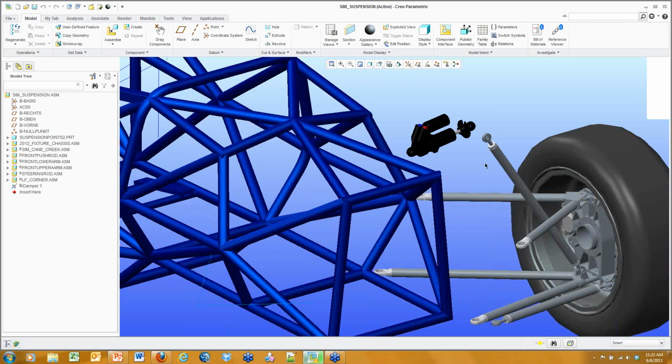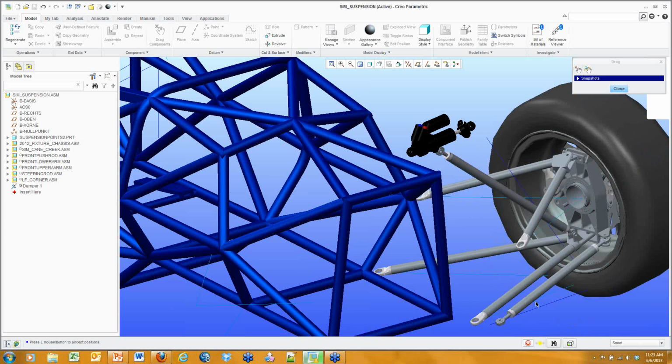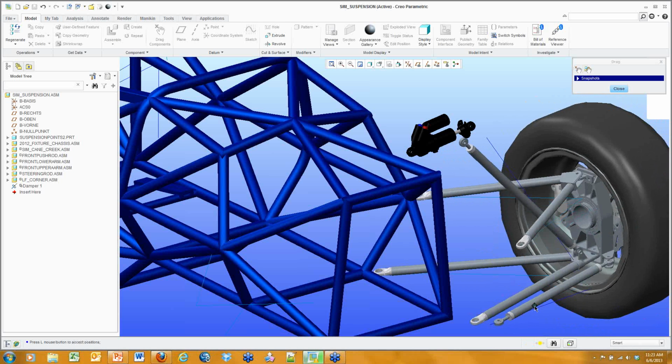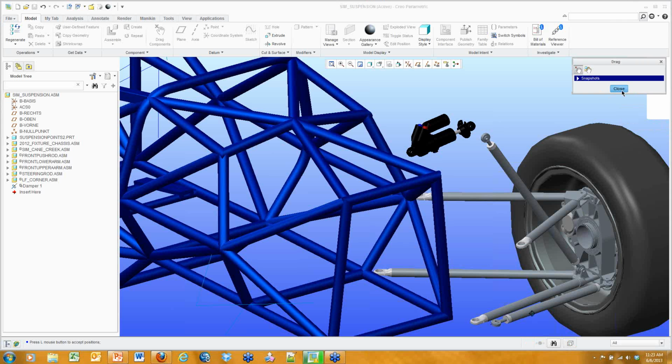What I want to do here is add an arm right here that's going to attach this strut to this shock absorber. And what I actually want to do is I want to see the stresses that are being put onto all of these parts. So first things first, let's just see how everything moves. So if I select this steering arm here, you can say move it back and forth, move it up and down. But really, this upper strut is just kind of floating in space because there's nothing to actually align it to.